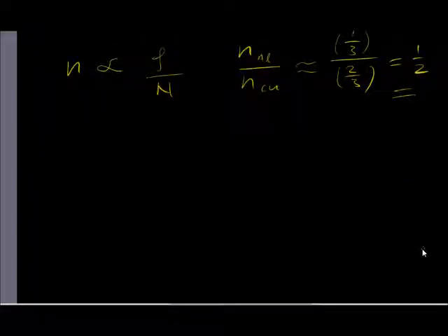And the second part, steel is an unsuitable material for the cable. If we look at the table, we can see that the resistance of steel is 210 ohm per kilometer, and it is much higher than aluminium and copper. So based on this, we know that the resistance is too high, and that's the reason why it's unsuitable. Alright, that's all.